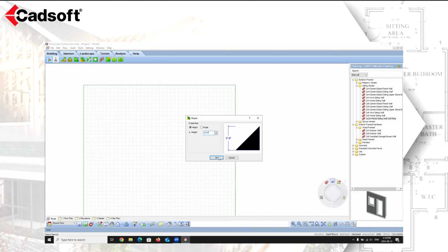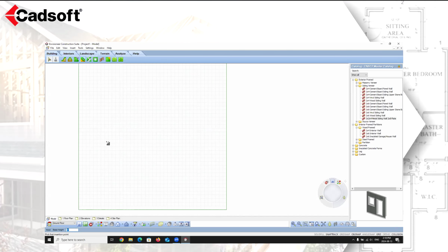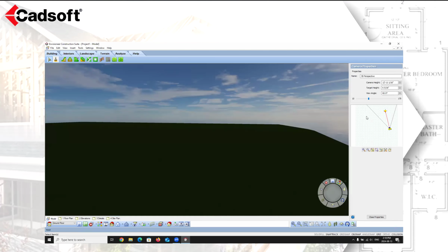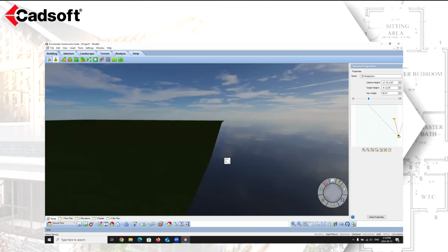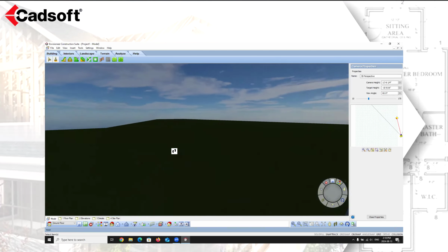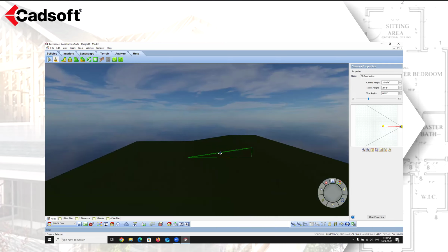And we're going to say, okay, so this is creating a slope of 8 feet. Now, wherever I start my arrow, so if I start my arrow here, right in the middle of my design, and I move it in this direction, it is going to slope that terrain up from that point. So my 0 point is the start point. So wherever I started is at 0, and then the end of the arrow is the upper point. So it's going to be 0 up to 8 feet.